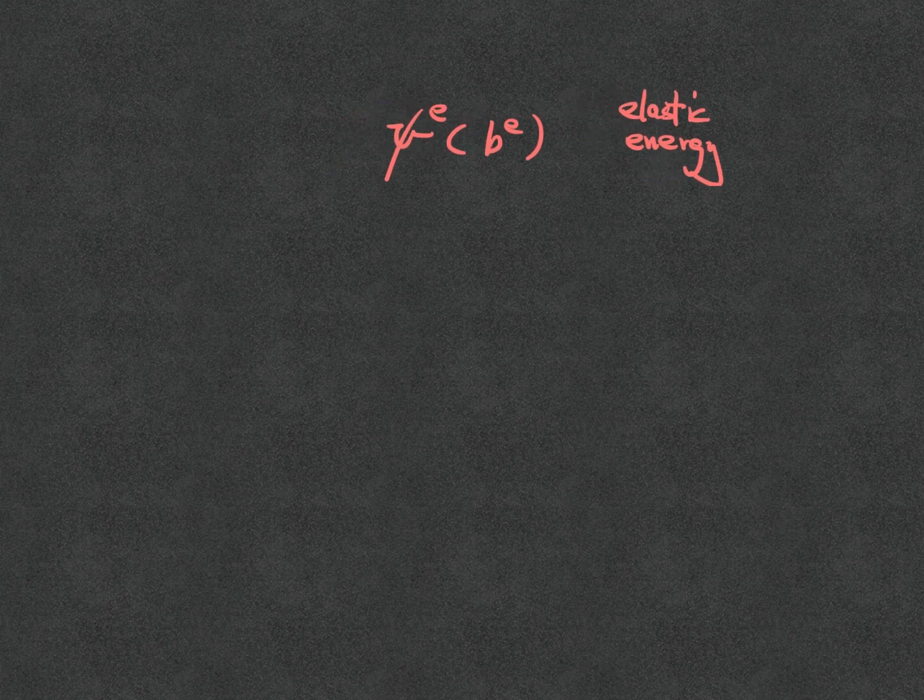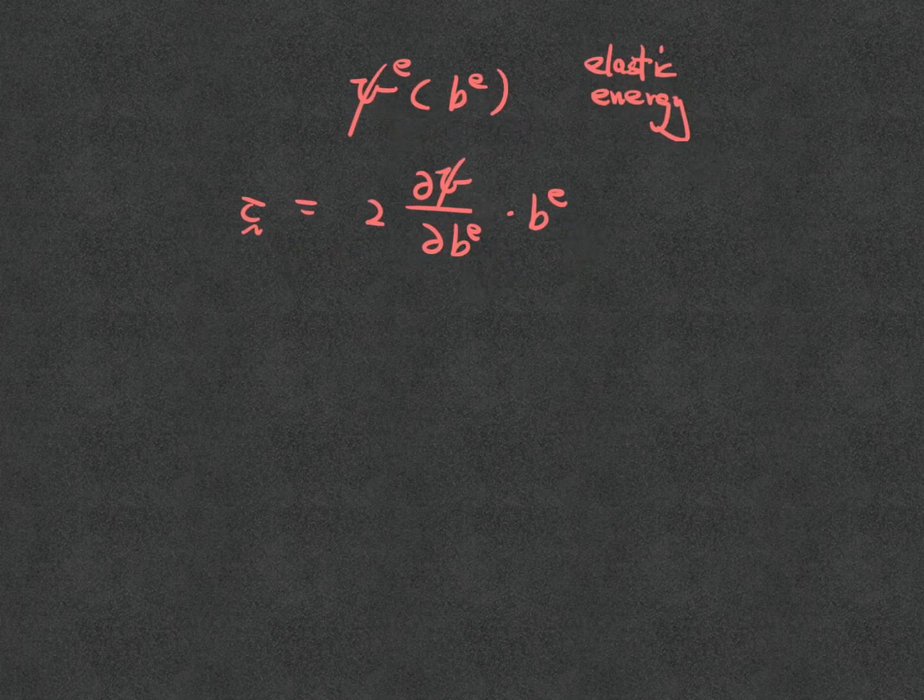Okay, so for the large deformations, I would relate that B with the Kirchhoff stress, which has this funny shape. If I take the derivative of the elastic portion of B, times B dot, I will get the Cauchy stress. Now B^e is equal to F^e F^eT, and F is the combination of the elastic part and the plastic part in a multiplicative manner.